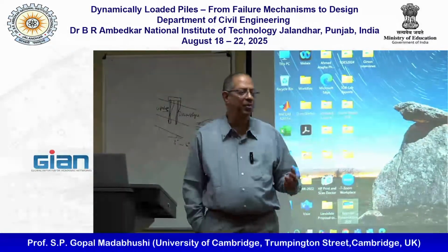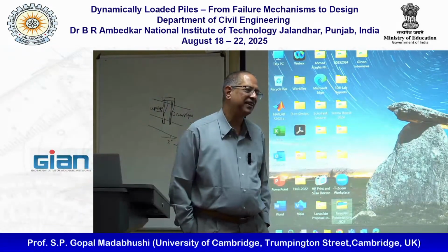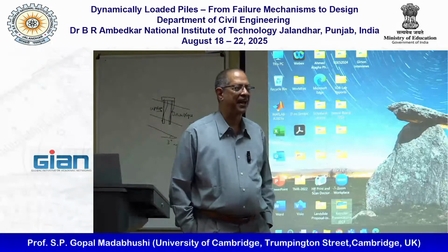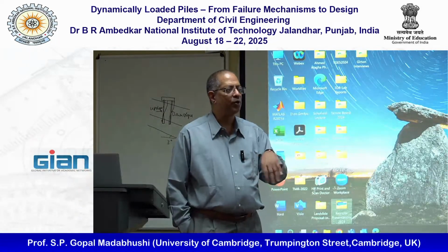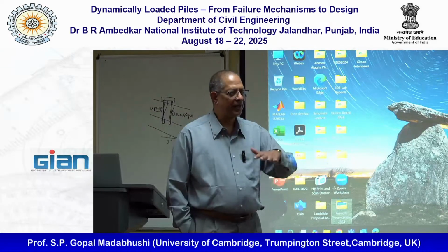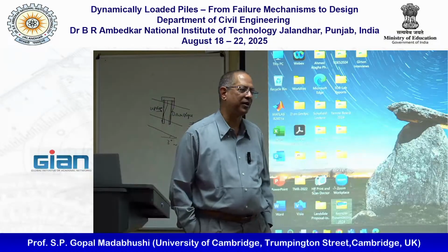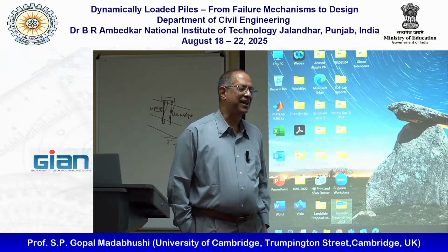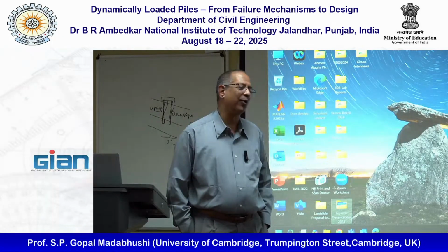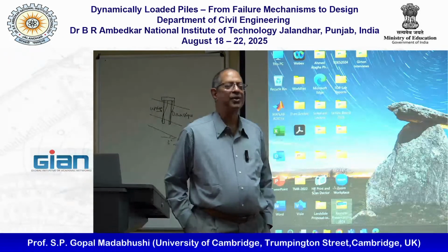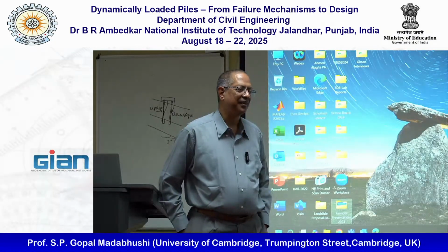Even saturating the models with methyl cellulose is all a computer controlled process. There's a thing we developed called CAMSAT, which keeps the flow rate small enough so that you don't fluidize the sand and slowly lets the fluid in. It takes about 8 to 12 hours to saturate these models because you're trying to saturate them with 50, 100 centistokes fluid, right? So it's going to take a long time. When I was a student, we were doing it manually, and I would stay all night long in the lab. And I thought, this is ridiculous.